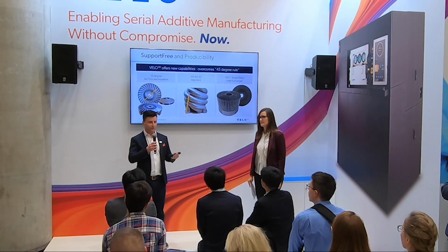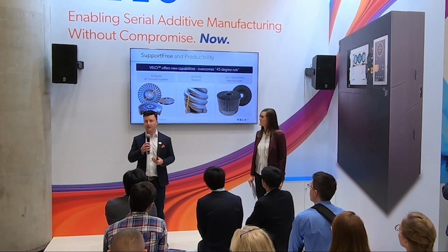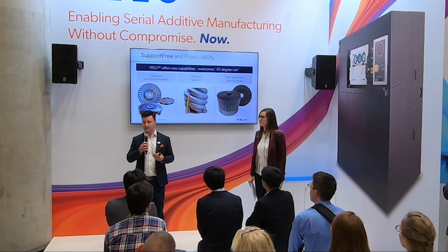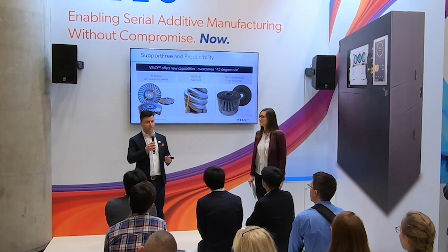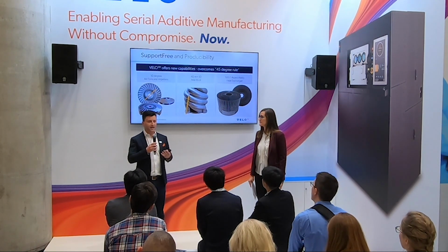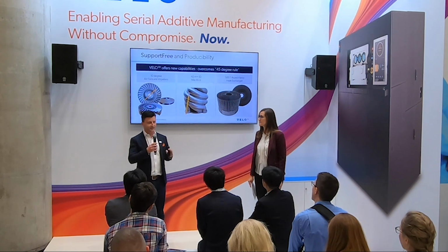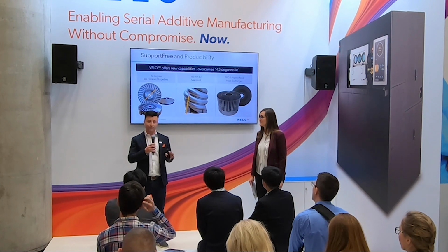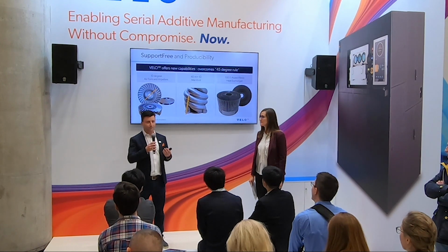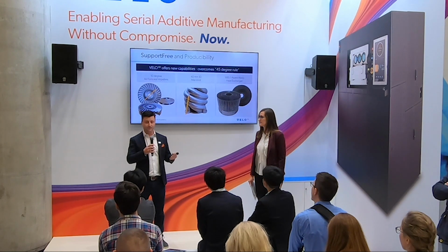Producibility of a single geometry is a good first step, but when you get into the discussions around qualification and certification, the repeatability makes a big difference too. One of the things about producibility that you have to consider is yield, right? So you have scrap rates, you have rework that have to happen as part of the producibility. The way this is addressed most commonly in metal additive is if a geometry is on the edge of being possible to print, you'll often over support it. You'll add enough supports that the part will print well the first time and will continue to print thereafter.